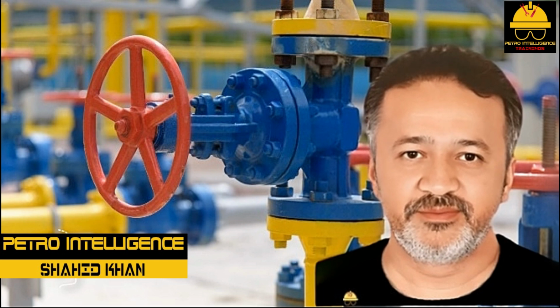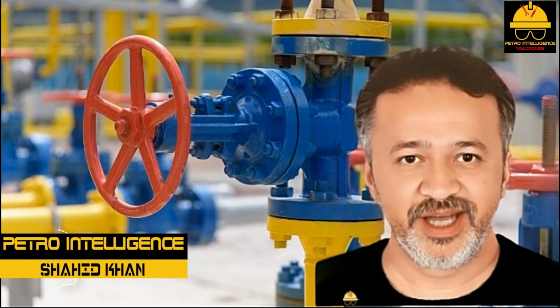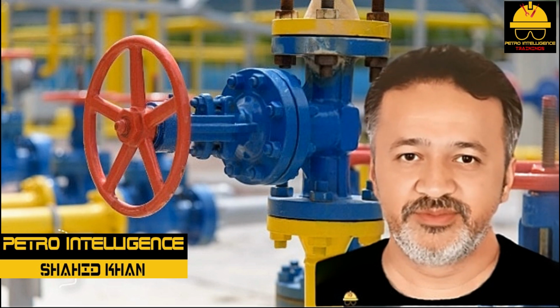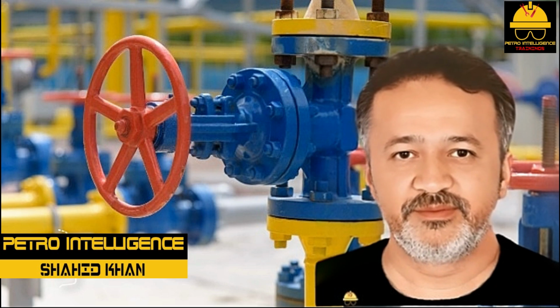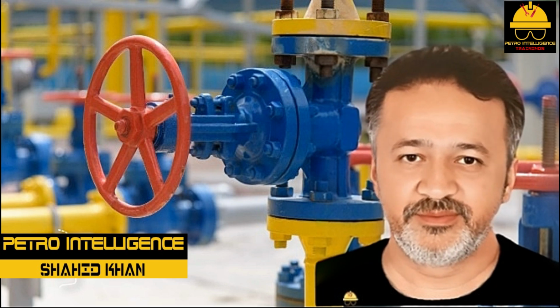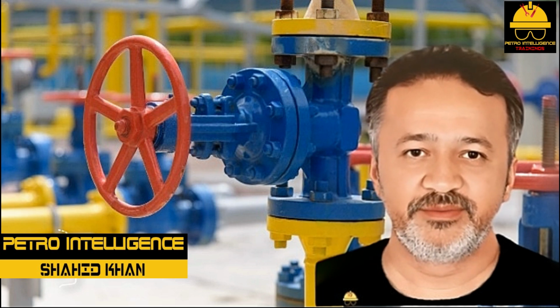Check valves. A check valve is designed to prevent reverse flow and to avoid possible contamination or damage to equipment. The check valve limits backflow but is not considered a tight shutoff. Check valves come in a variety of designs and applications. Check valves have flow direction stamping on the valve body.